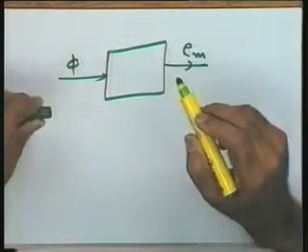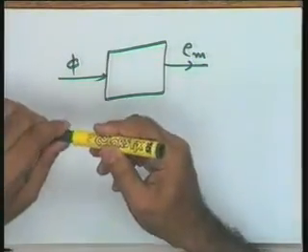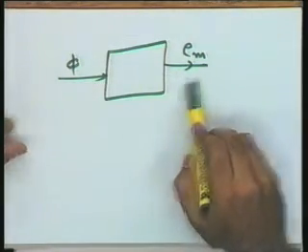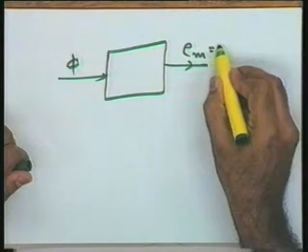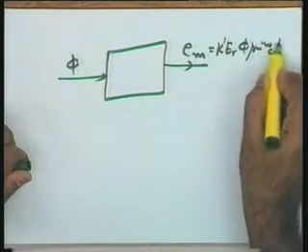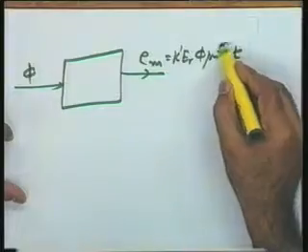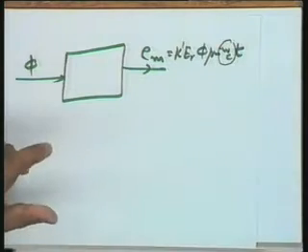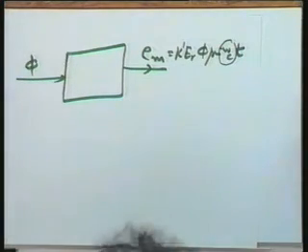Now here I need your attention, please. If I want to derive a transfer function model for this system, where input is phi and output is Em, and you will recall Em is equal to K' Er phi sin omega_c t, the mathematical model is going to be complex. However, at this juncture I will use the information that omega_c is simply a carrier, which is the operational frequency of the device we are going to use. 50 cycles, 400 cycles per second, 1000 cycles per second are the typical frequencies used.